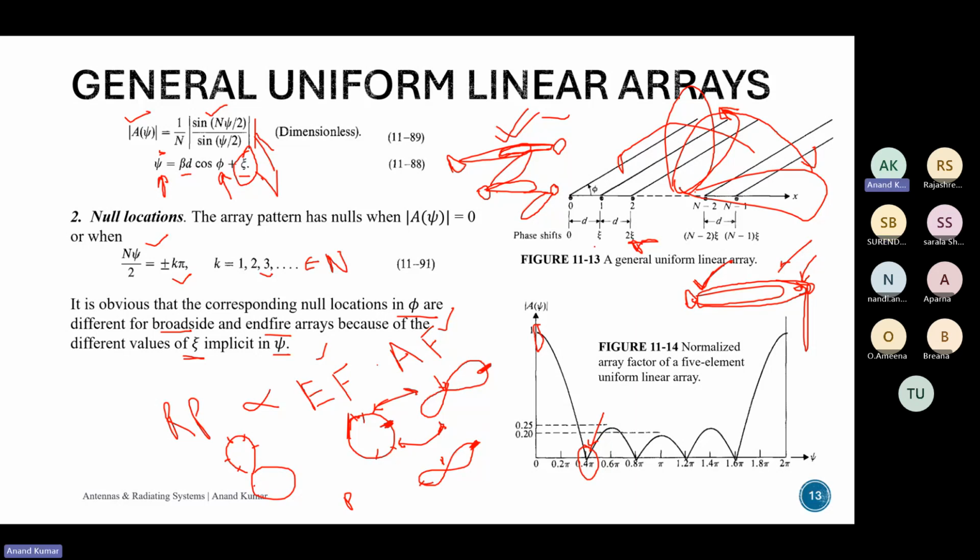Grating lobes. Okay, a new term. If I remember correctly, if this is the radiation pattern, like for example a horn antenna, it looks something like this. So these are the grating lobes, right? Grating lobes are equal or approximately equal to the main lobe. What you drew are the side lobes.